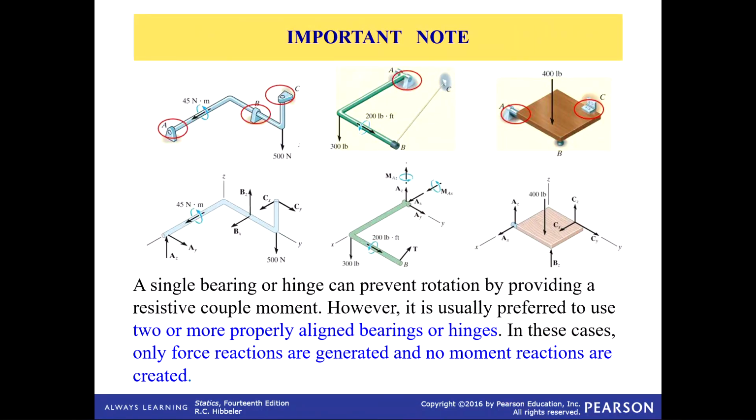You've got a couple of bearings, and those look like they're probably sleeve bearings in those particular cases. So you can pull them out or you can spin. Well, you can't actually spin in this particular case because the other two bearings prevent the thing from spinning.